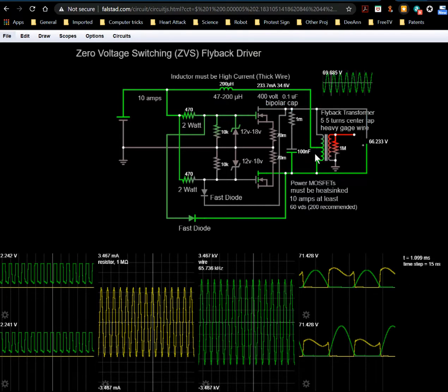measure the resonant point of a circuit, you can just take a capacitor of known value and an inductor of unknown value, for example, because capacitance meters are easy to find. So if you don't know the inductance, you can get an idea of it by taking a capacitor and an inductor, and, like I said, actually apply power to it just temporarily, but then have a frequency counter hooked up to that, so when you remove power, it counts the frequency.